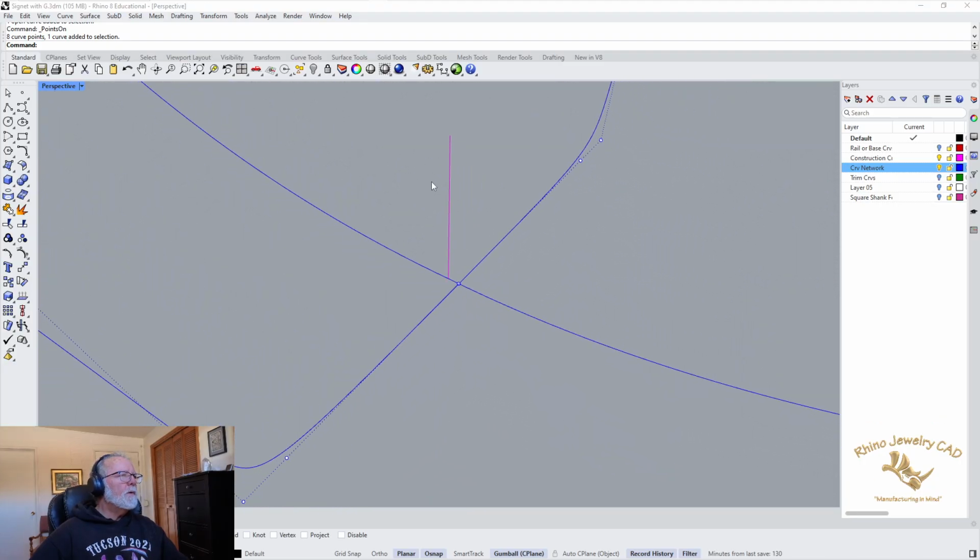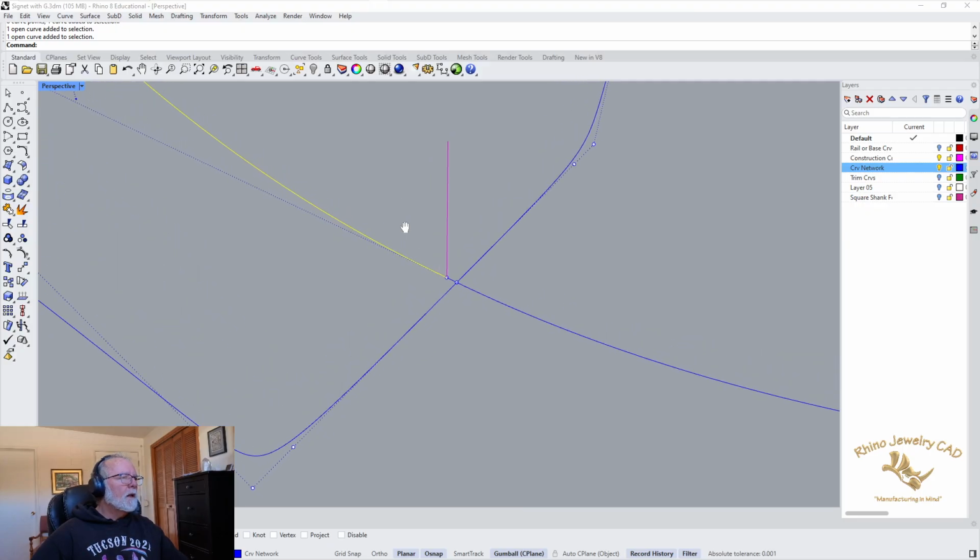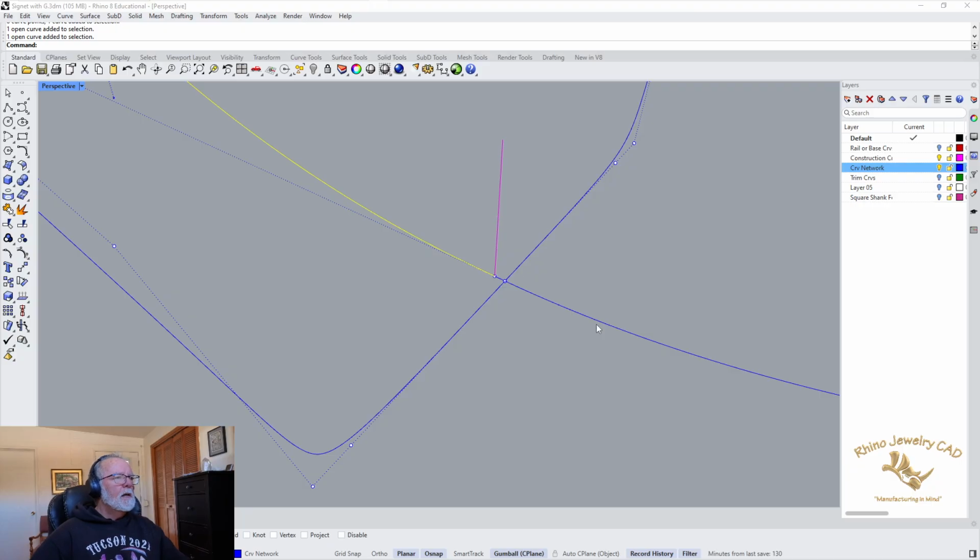So what we see here was my construction line that I was trying to hit. And in previous versions of Rhino, that was always the quad. Well, now for some reason, although the endpoint of the left side rail, I'm calling it the left side rail again, and the right side, which was mirrored from the left side, of course, both endpoints are going to be right here where they were supposed to be, aligned on the Y axis.